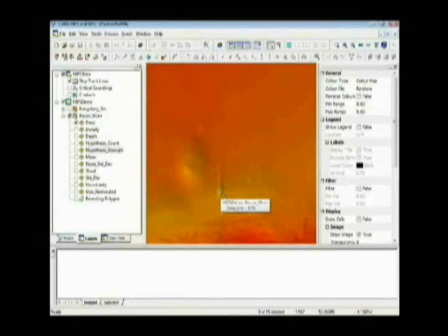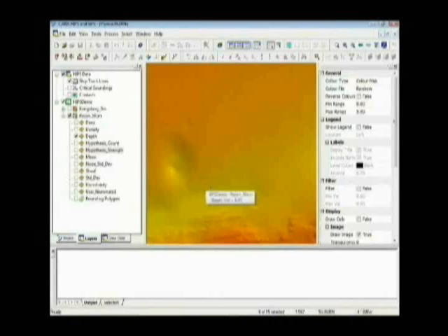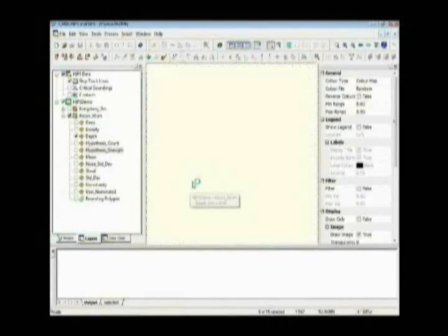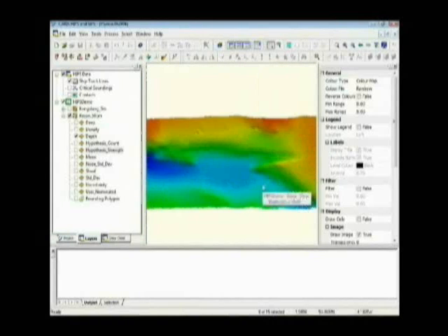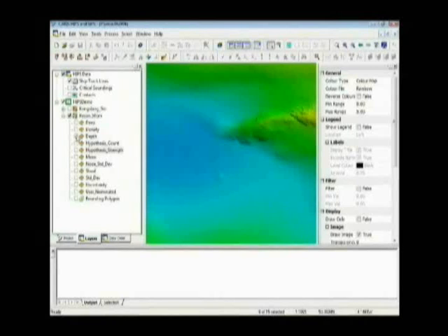So here, using my tooltip, I can see that the sounding depth, or the deepest sounding for this node, is about 9.74. Turning the depth layer back on, this is no longer visible, and I've got a depth of about 8.5 meters. This is true with other areas in the surface as well. By switching between the deep and the depth layer, I can see that I get other features.